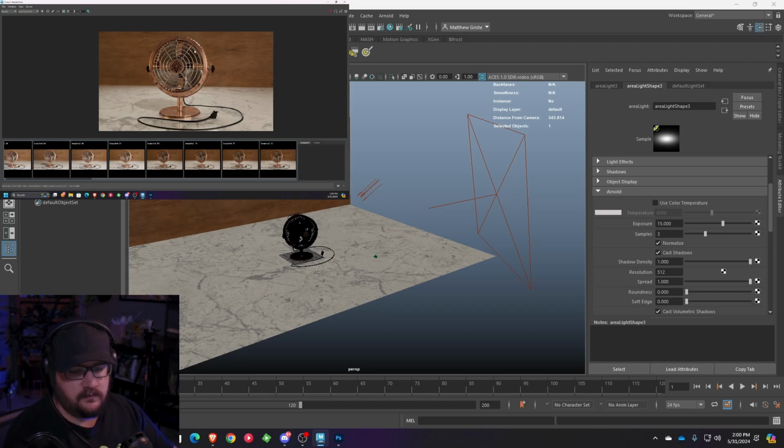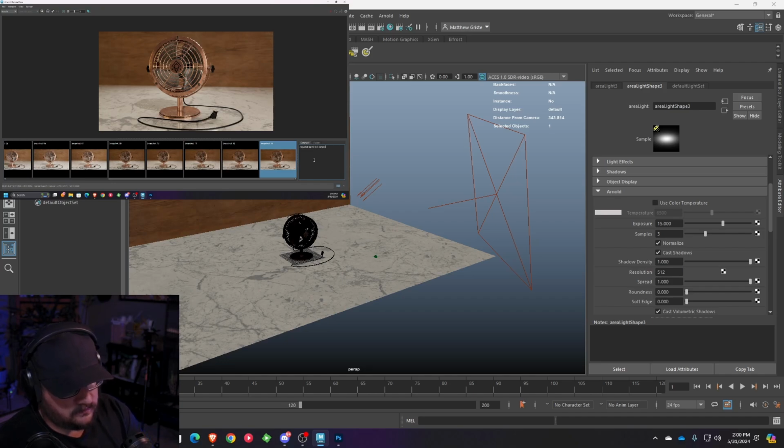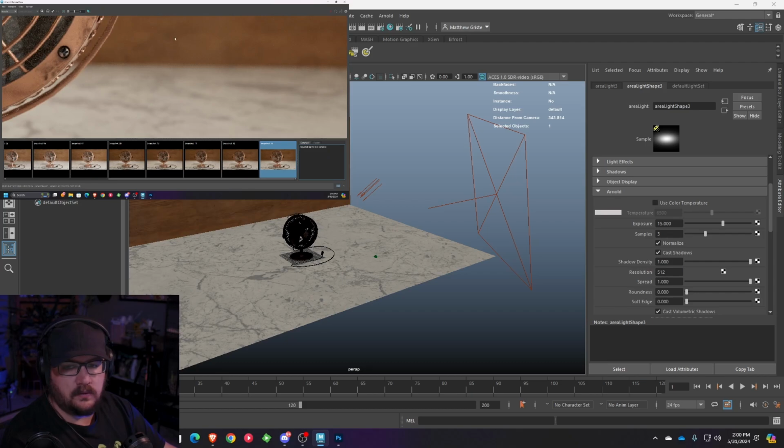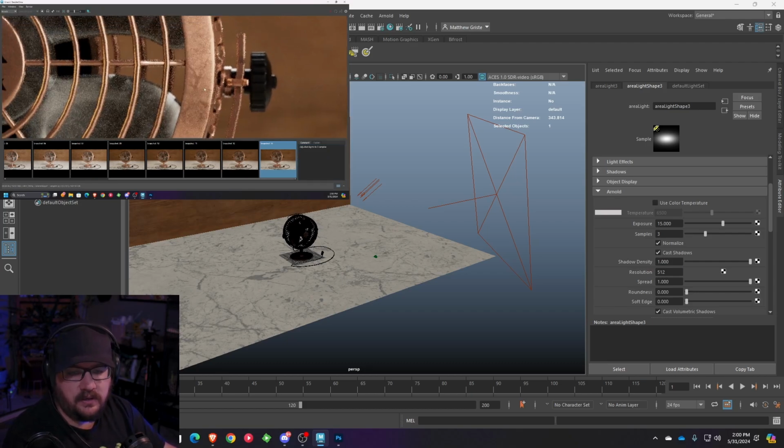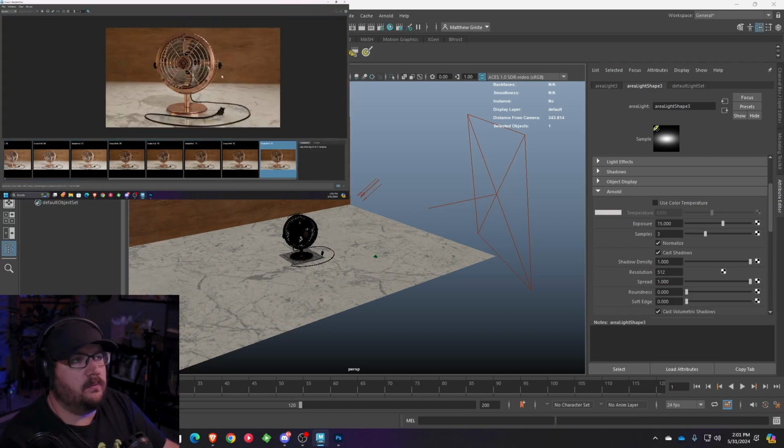Okay. So we go ahead and save that snapshot. Adjusted lights to 3 samples. Okay. If we zoom in, you can see we still got grain. There's still quite a bit of grain, and that didn't change a whole lot. It changed a little bit. It did help. This is one of the cases where you can go through and change samples all day and really adjust things and clean things up. But in the end, we're talking about a tiny bit of noise.